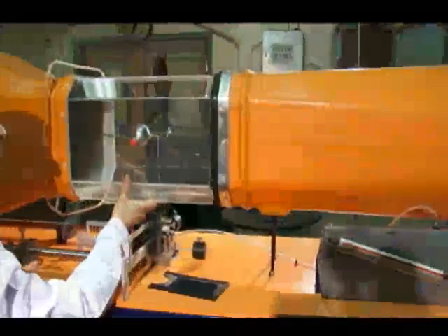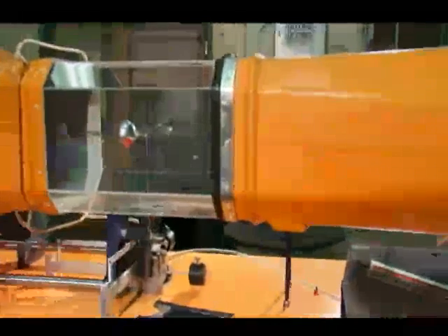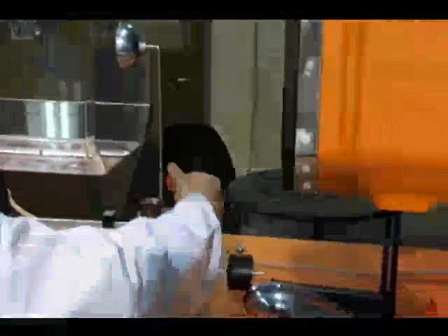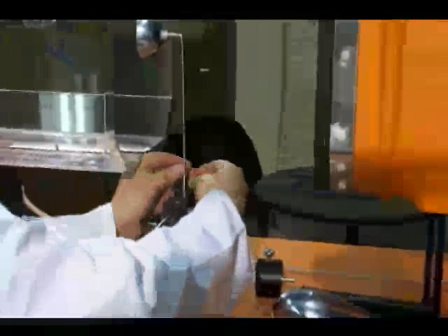The contraction cone chamber contains an aluminum honeycomb flow straightener designed to ensure that the flow is steady in both magnitude and direction, and it has a flat transverse speed profile. All models are to be tested in the clear acrylic parallel test and measurement section. To fix and exchange the testing models, the testing section can be opened and closed using a sliding guide.